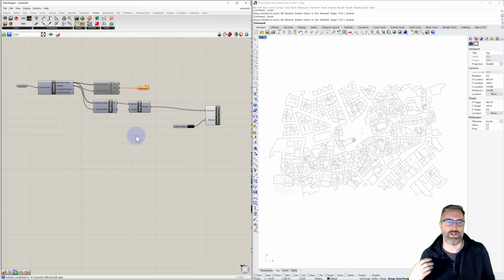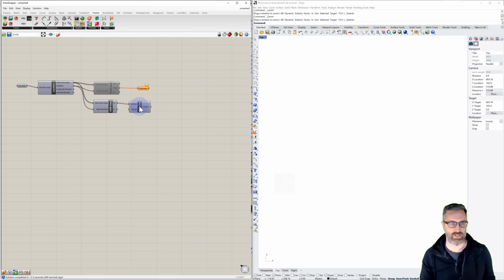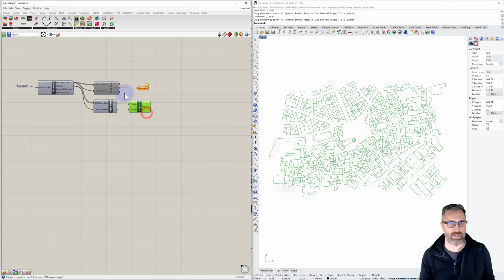All right, so you've brought in your data using ELK, and you've got a city plan that you want to work with. What I'd like to do now is to adapt some of this, because we don't actually need this kind of live connection to this database. I just want to bake this geometry. So I can get rid of the display. I'm going to keep the polylines, but I'm going to bake this geometry. So we'll bake this. And actually, before I do,